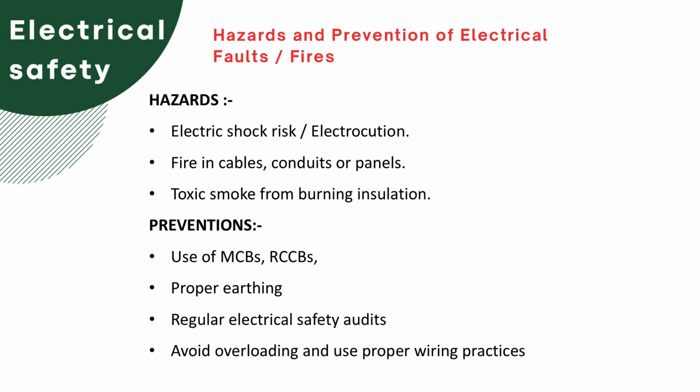Now, next one is very important, and you must go for a regular electrical safety audit, because in an audit, the auditor knows the electrical norms. He is a well qualified electrical engineer or a chartered electrical engineer with experience, who knows how a particular factory or office should be designed, and according to the load, what should be the ratings of your cables and ratings of your circuit breakers.